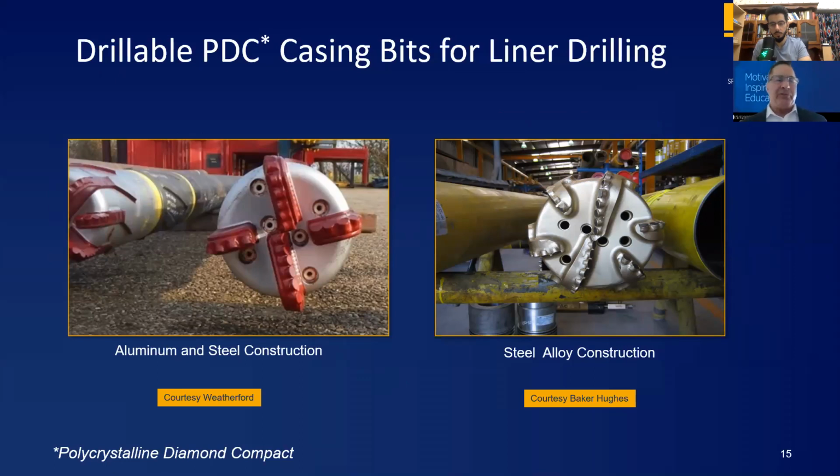And I know there's been issues in some of these shale basins where hydraulic fracturing, they say, is responsible for casing failures. Well, you don't want to have damaged casing in the hole prior to fracturing. This could be some type of mechanism for less life of the casing during fracture jobs.